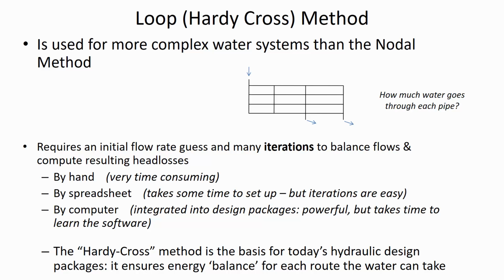And you have to have the same amount of total energy at a single location, regardless of what route you get there. So just keep in your mind, it's easy to lose track of the big picture when you're doing the Hardy-Cross method, because there's so much detailed, intricate application of these abstract formulas. But what's happening in the background is we're balancing continuity and trying to get energy to work out, so that any one of the paths has the same energy loss, regardless of which route we take.